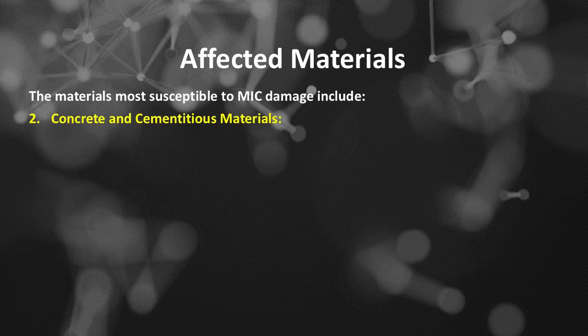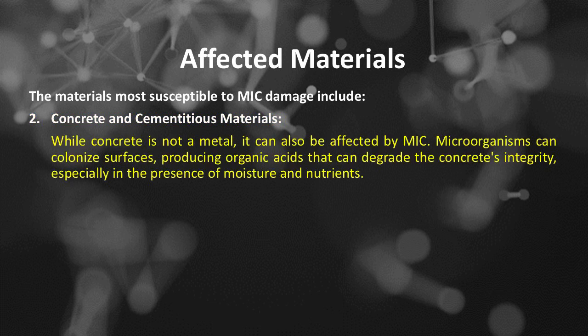Number 2 of the materials most susceptible to MIC damage is concrete and cementitious materials. While concrete is not a metal, it can also be affected by MIC. Microorganisms can colonize surfaces, producing organic acids that can degrade the concrete's integrity, especially in the presence of moisture and nutrients.